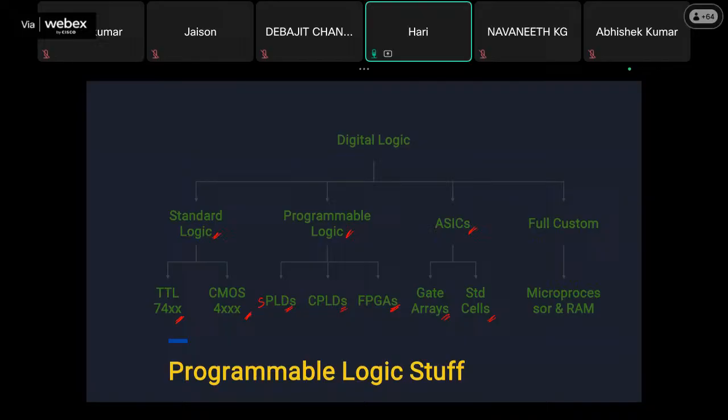As I said previously, we have one problem statement, and I am creating one particular IC to solve that problem. That is an application-specific integrated circuit, right? Those are realized using gate arrays and standard cells. Apart from it, we have full custom designs, which are microprocessors, RAM, and microcontrollers also, right? So those are full custom designs.